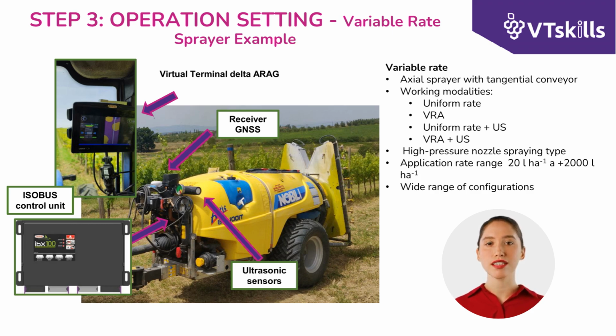For operation, it is necessary to create a spray map, which is generally based on vegetative development, such as tree row volume, or leaf area, such as leaf wall area, in vector format, to be uploaded to the machine via a flash memory. Maps can be created using smartphone applications like iAgro or other free platforms like AgriSat.